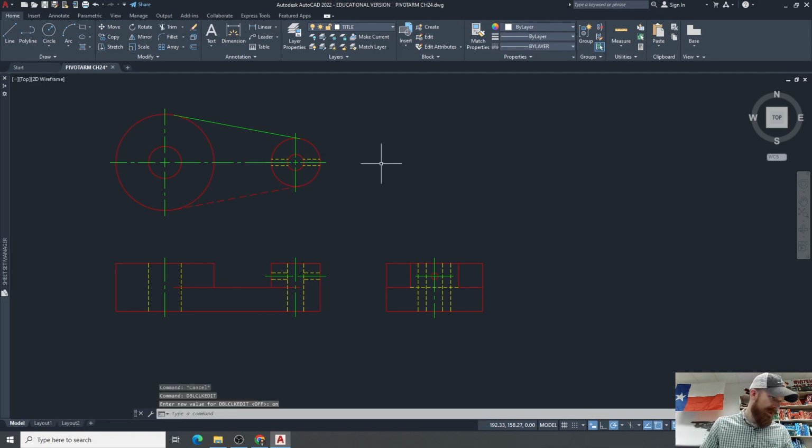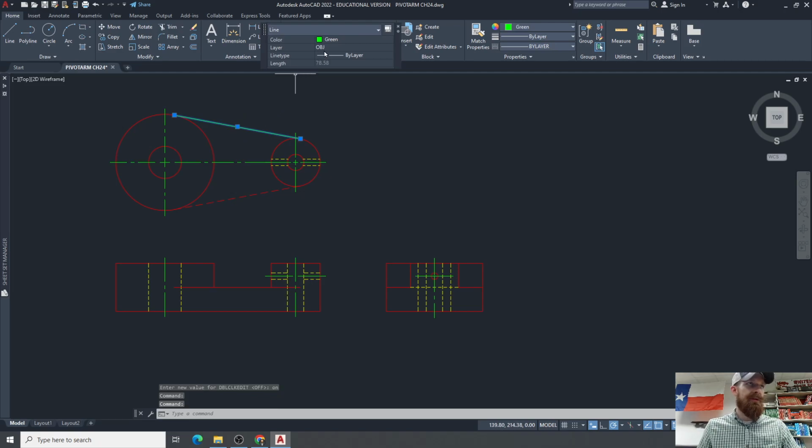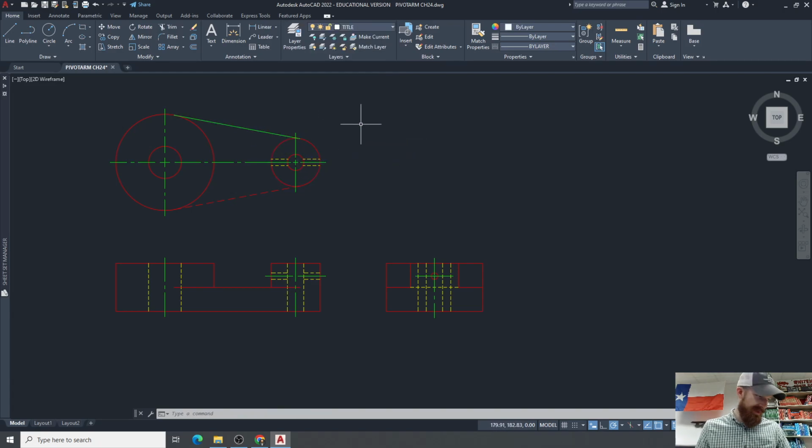Very good. Okay, so just a minute ago you saw this layer tool, right? By changing an object's layer, the selected object is effectively moved to the designated layer. In doing so, if the object's color, line type, and line weight are set to by layer, the object assumes the color, line type, and line weight of the layer to which it is moved, right? So it operates by different rules. So my layer is object right now. If I went to, I don't know, let's see, def points or something, this might have different rules that the line goes by, right? And there's layer, color, line type, scale, thickness, line weight, all kinds of stuff you can get into.